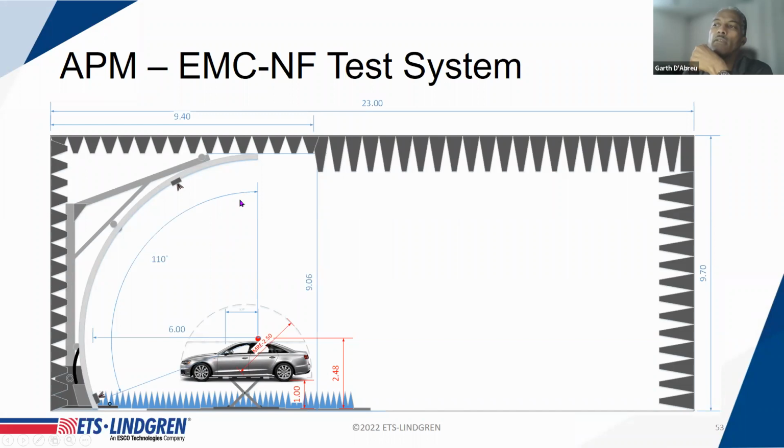But you're still able to get, in some cases, quite accurate peak gain measurements or peak pattern measurements with this type of measurement setup. As is the case with the EMC standard, if you really want to get an accurate pattern, then it's always possible to improve the quality of the measurement with a more optimized design of the chamber. But what I'm showing here is really what we're seeing in the industry from customers that are trying to come up with methods of meeting a particular need, without having to go out and do ridiculous things to get quite acceptable results. And I think that's the true essence of engineering.